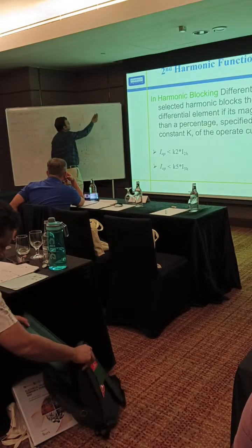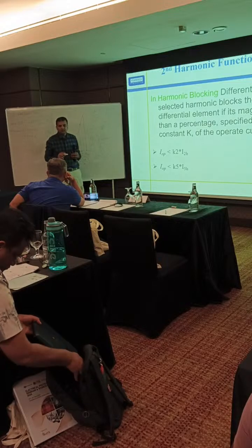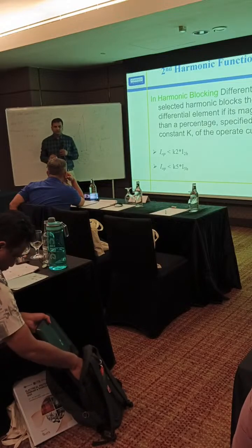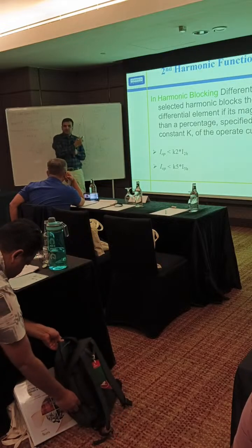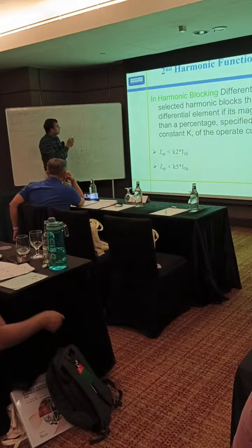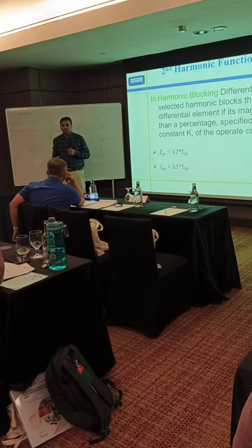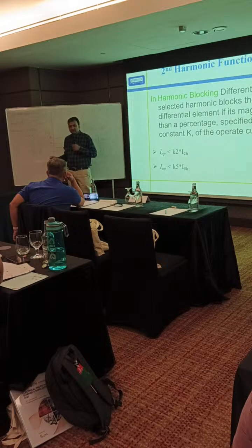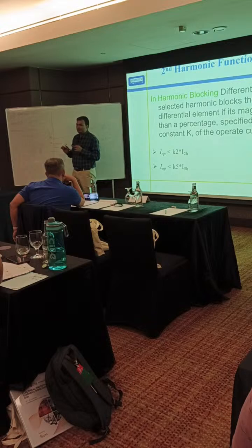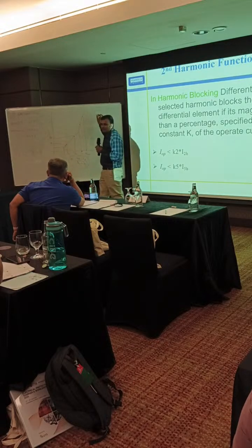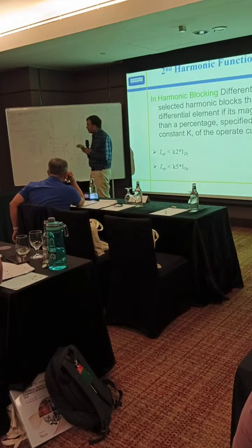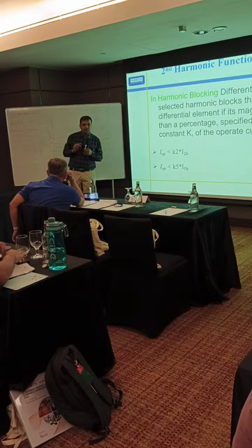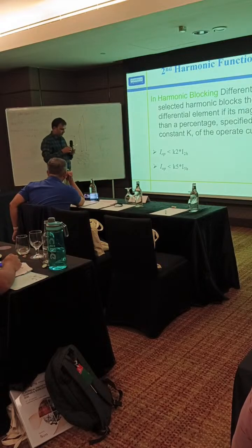Okay. So it is generally a confusion when you are testing. That is why I asked this question. So generally we do the testing at rated current. If you want to test easily without being confused, always inject 1 ampere, so it will be 20% injected. Okay. So this way you can test the harmonic. Basic understanding.